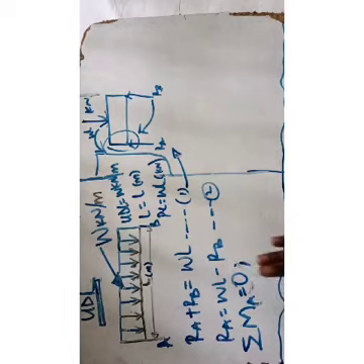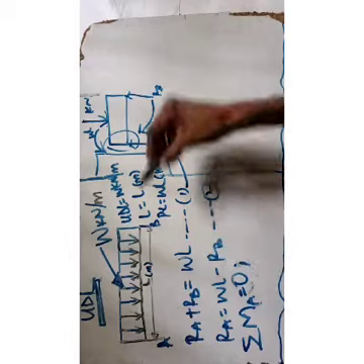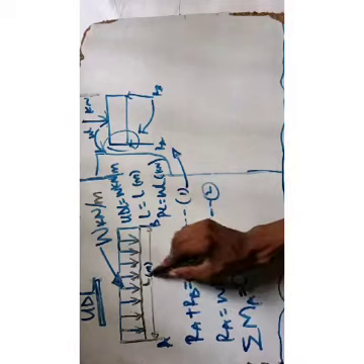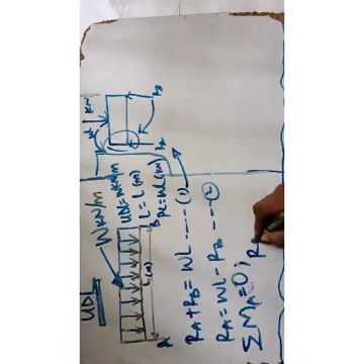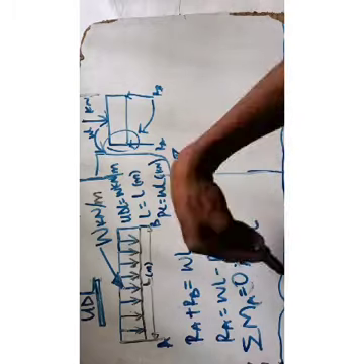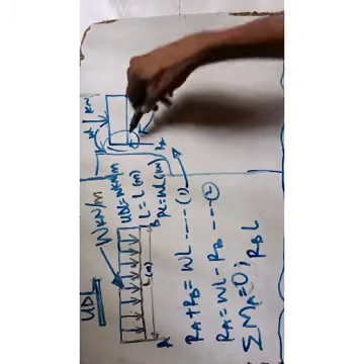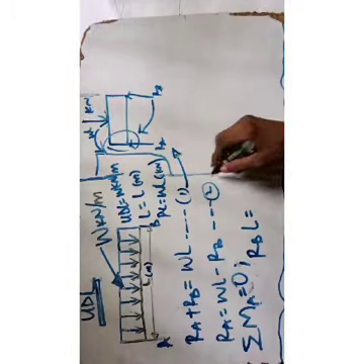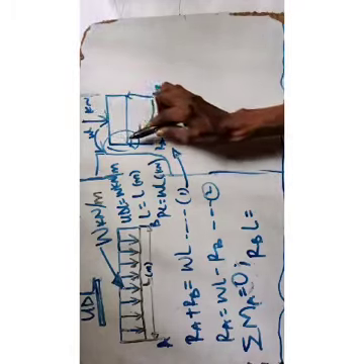Then if you want to take moment at point A, what you do next is you redirect all the force back to point A. That would now be RB times total length, okay? RBL, right? Clockwise is equal to anticlockwise. So that will be RBL equal to what? Complete that. Your WL times what?